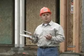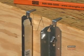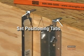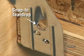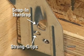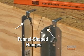The IUS series hanger is a unique hybrid hanger for I-joists. It is versatile like a face mount hanger, but is easier and quicker to install like a top flange hanger. Also, it doesn't require joist nailing. An IUS series hanger is like a face mount hanger, but it has additional features that ease installation. For example, the IUS series hanger has set tabs on top, a snap-in teardrop, which replaces the need for joist nailing, strong grips to hold the bottom chord in position, and a starburst to secure the joist in the hanger seat. An IUS series hanger also has funnel-shaped flanges at the top to guide the joist into the hanger.